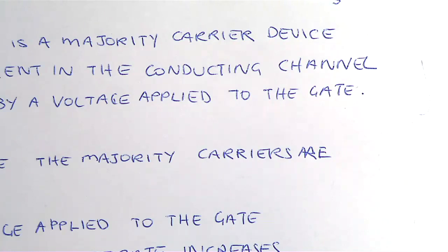Predominantly what I'm going to focus on in this course is actually MOSFETs. Now, I believe that in a lot of your lectures, people are still focused on BJTs, is that correct? Bipolar junction transistors. I'm actually going to focus on MOSFETs, because if you're building any kind of semiconductor product or logic-based semiconductor product, it's going to be CMOS-based.